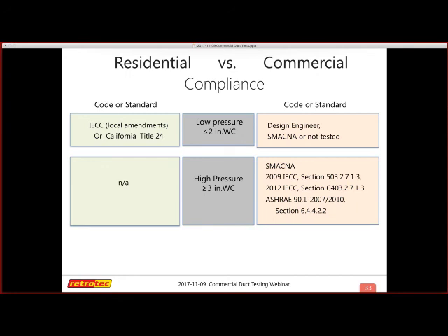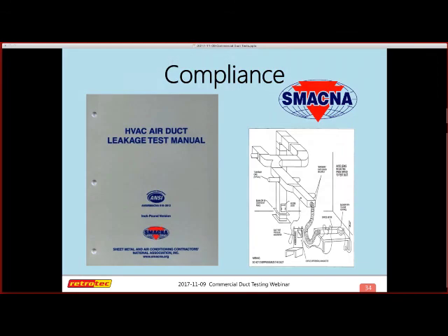So if you can see by the illustration on here, it's a pretty old-school type of concept. In fact, what it looks like, and what some people actually do use, is a leaf blower. A leaf blower will create an enormous amount of pressure for you, and then between the leaf blower and your flex duct, there's an orifice. Again, back to this calibrated orifice. If I know how much flow is going through the orifice with my leaf blower, then I can determine what kind of leakage it is. Okay, so it is a very loud and homemade kind of concept.